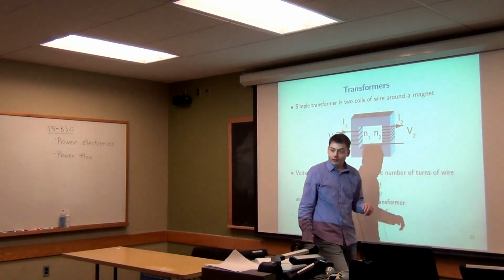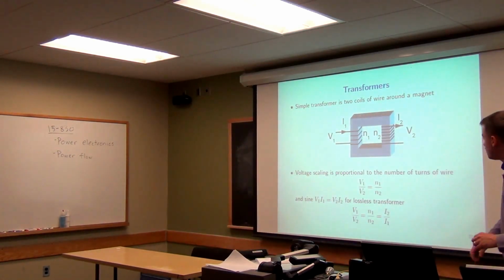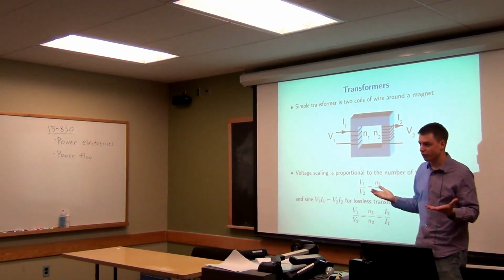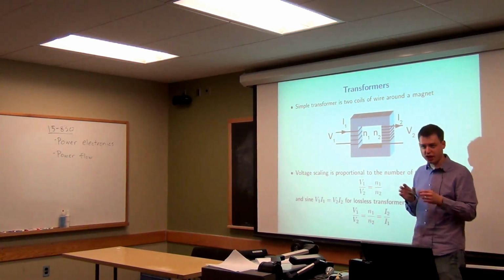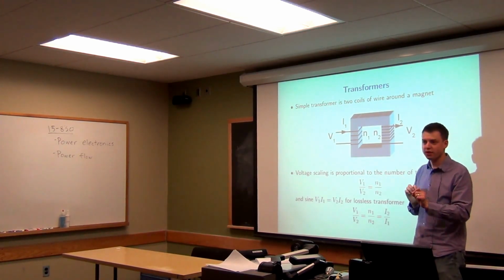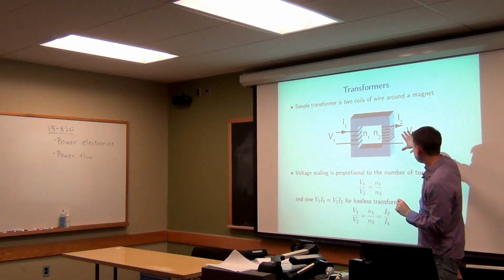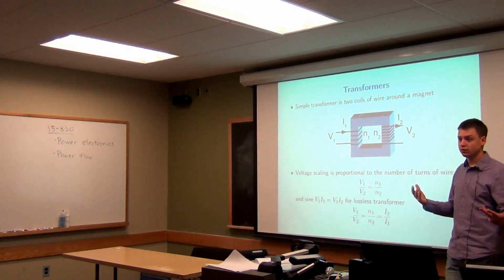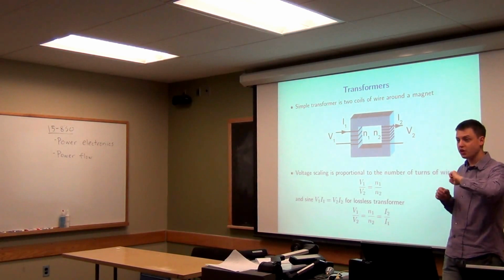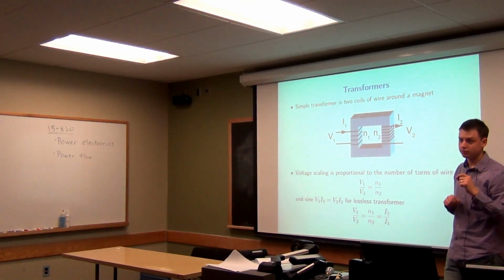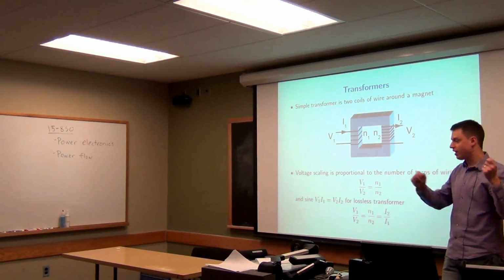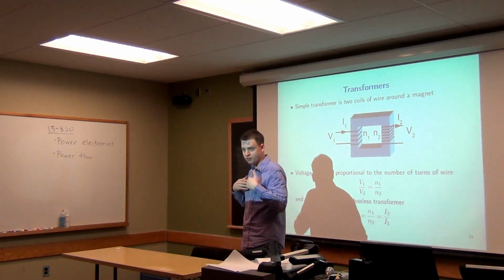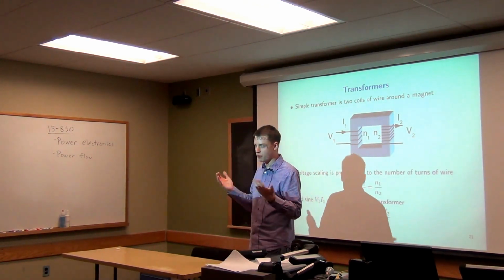What you can do instead is create transmission lines that have very low current. There isn't that much current flowing through them, so they're going to have very little losses in the wires themselves. And you do this by stepping up the voltage to be really high. You make the voltage really high. That has to bring the current down. And so on the transmission wires, you have very little current flowing. If we had those transmission wires at the same voltage as we have in the actual outputs here, that would be a disaster, because there would be so much current that would need to flow through these wires, you couldn't do it, they would burn up.